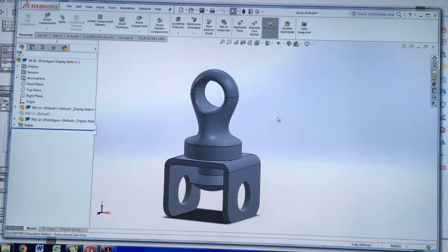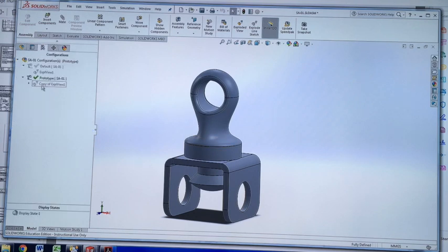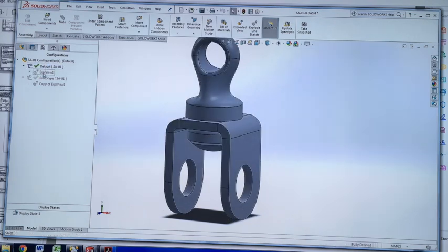How did you copy the exploded view again into different configurations? So in the configurations, you can only copy it from the current configuration, so you have to be on the default one. Then you just select the exploded view and drag it. Once it drags, you see that little arrow, basically like an arrow plus sign. That'll copy once you release the mouse. That's it. If you're not able to get it, I'll be able to show you later on.